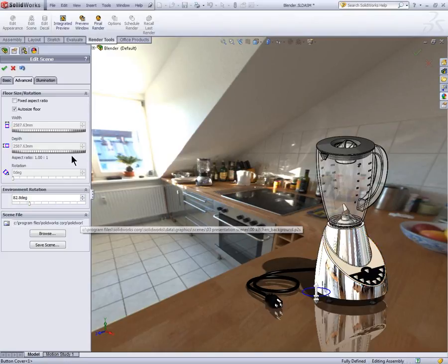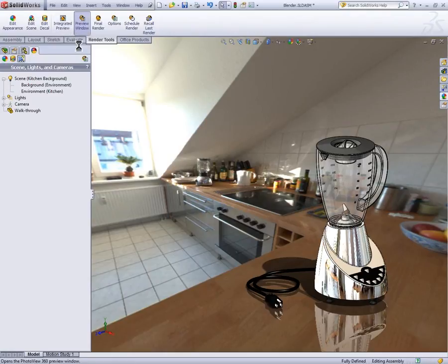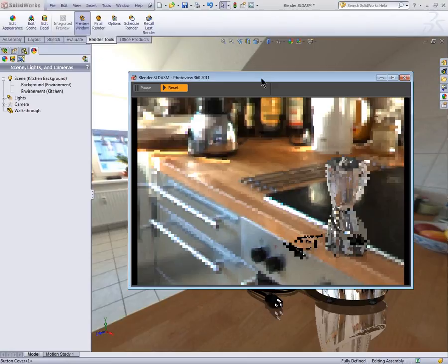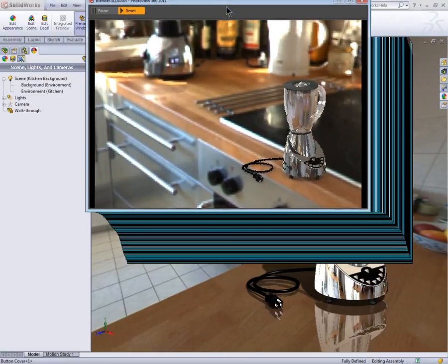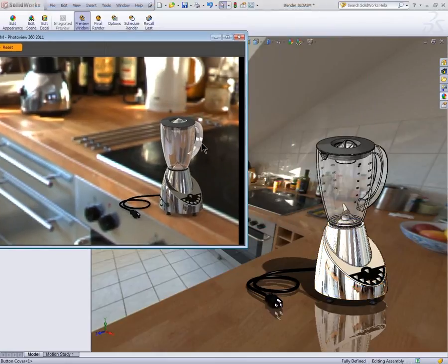Okay. Getting into the illumination side of things, we can actually have the environment give more of a lighting effect. This one actually shows better if I have the preview window going on here. Another thing to point out, always use your preview window for positioning, because see how I'm over in this one area, but yet the finished preview is actually over on the other side.